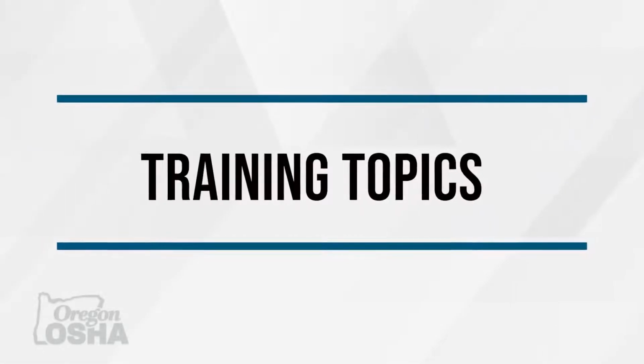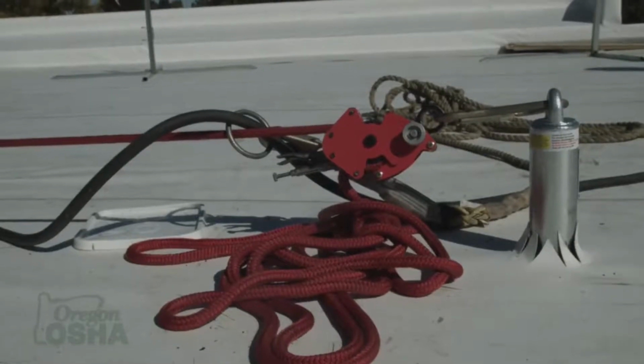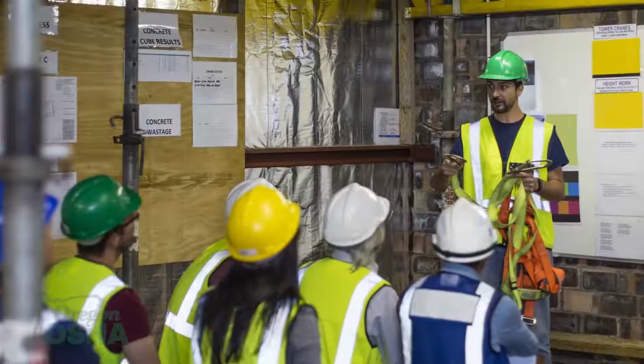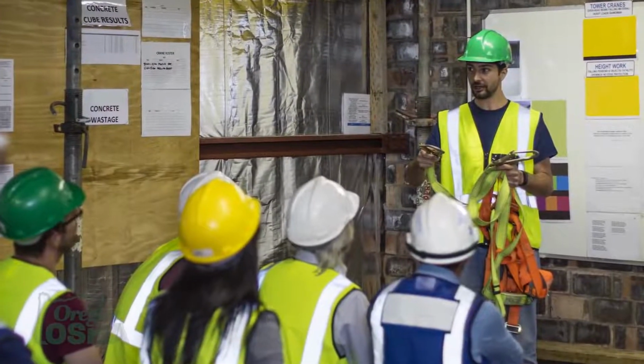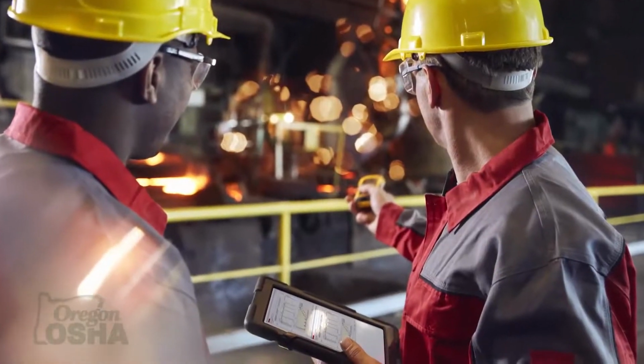We need to train workers on how to figure and calculate their fall clearances and their fall distances correctly, how to look at the devices that they're being provided and come up with what that needed fall clearance is, and also train them on how they need to anchor and where their anchors need to be so that they're staying adequately protected. They need to be trained on all the different areas where they are going and working at heights, on what the approved anchor points are in those areas. They need to be trained on the difference between fall arrest and fall restraint. We need to train workers to be more competent in thinking, can I bring up an idea of guardrails here?